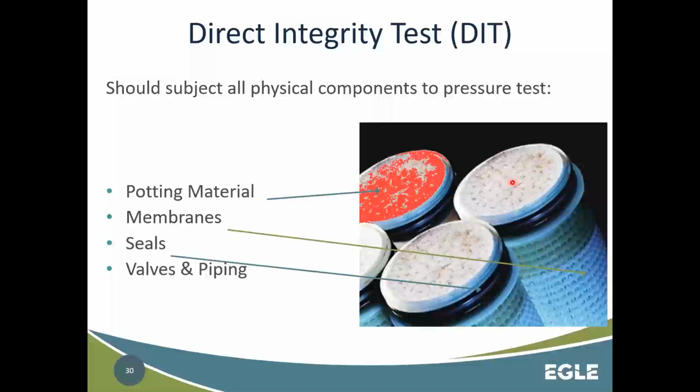If you got a crack, this is hard. If you were to feel it, it's a cured resin there, so it's a hard surface. You can knock on it. If that were to develop a crack, which I have seen happen, again, you have raw water that would totally bypass. So all of those different components need to be part of that direct integrity test. And that's not something the operator does. That's something that is designed by the manufacturer. And if it's not done that way, those challenge tests would be a failure and they would never get approved to be on the market.